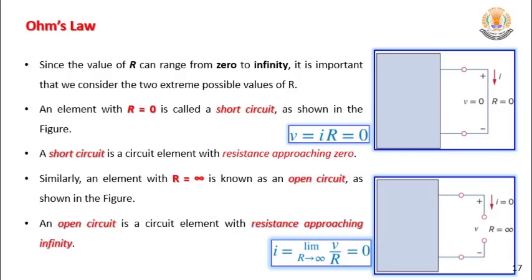What's meant by short circuit? You connected both terminals together. You connected the positive with the negative. This means the voltage will be 0. Okay? But why? Because the resistance is 0. You have no resistance, you connected the two terminals by a wire. So the resistance between the two terminals becomes 0. As a result, the voltage will be 0. So in short circuit, the voltage is 0.